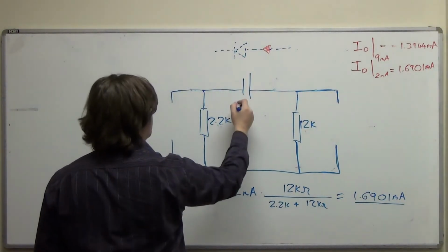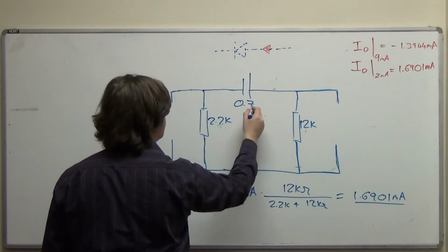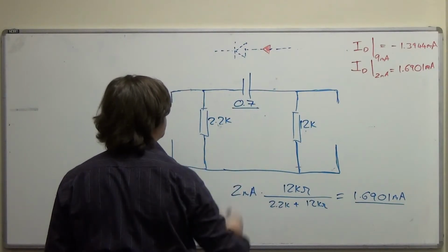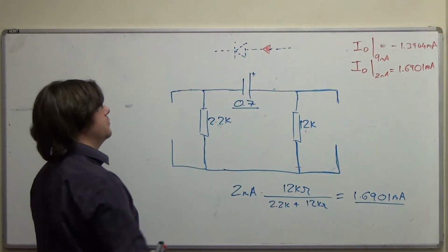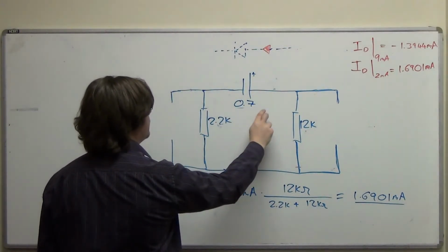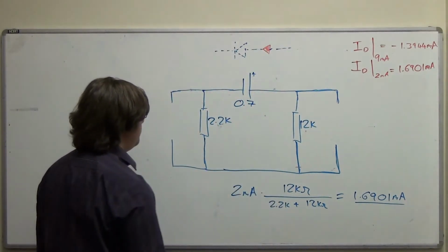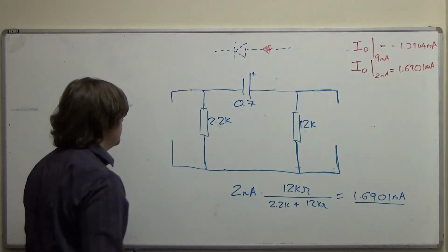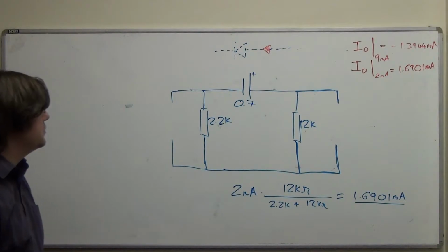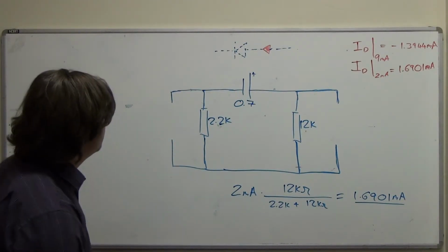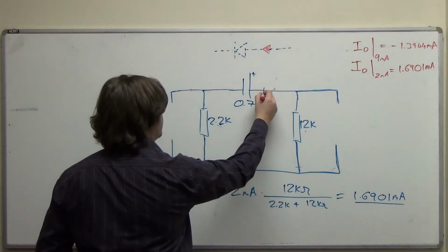And this has 0.7 volts across it in that direction. But we know that because this is the big one. You can put a plus there if you really want to. So I shan't put an arrow because I don't usually. That's 2.2k. So well, in this case it's a nice circuit with two resistors, and what we really want is the current that's leaving here.